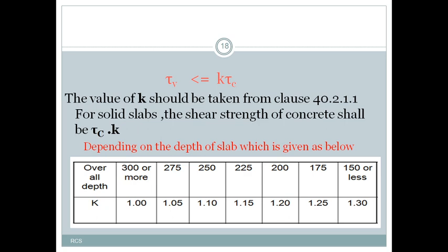So those bent up bars will act as shear reinforcement. We have to bend 50% at the left support and 50% at the right support to make it symmetric. Those are sufficient for resisting the shear forces coming onto the slab. There is no separate shear reinforcement designed for that. So in most cases we will not check shear and development length for the slab, but anyhow we are discussing it here because the bent up bars that we have provided are self-sufficient for resistance against the shear forces.